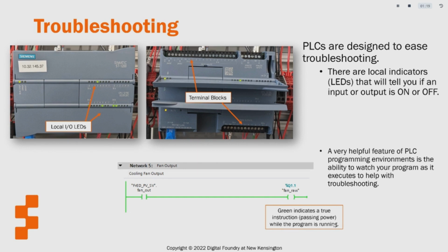As an example, if you're looking at your PLC and you expect a valve to be on, if the PLC output light is on but your valve is not, your program seems to be correct, but wiring may be the issue. If the PLC output light is not on, you should check your program as it is probably not correct. Note, readability by other engineers should be the primary aim of your program style. Avoid super clever code and comment very well.